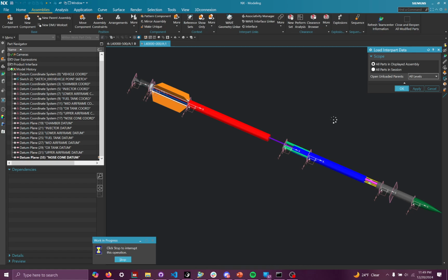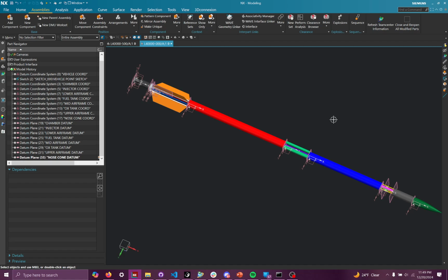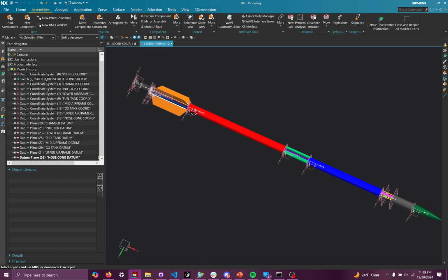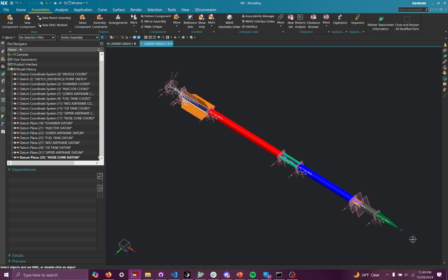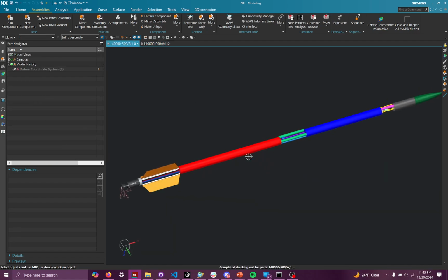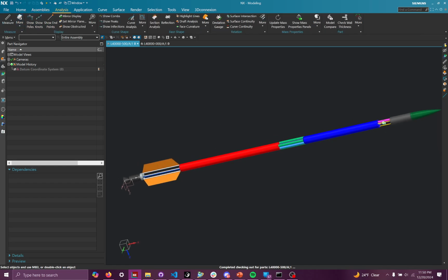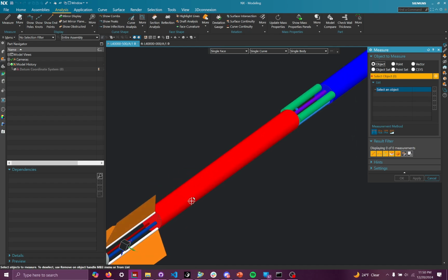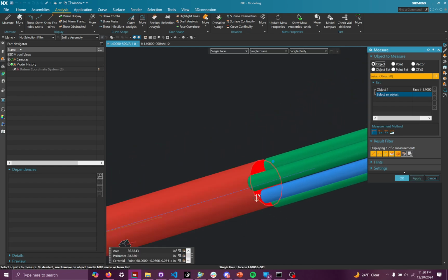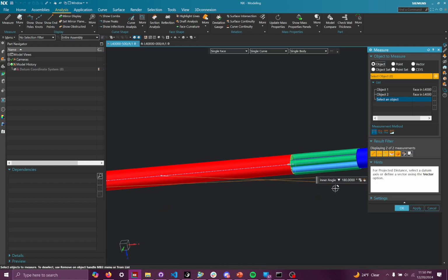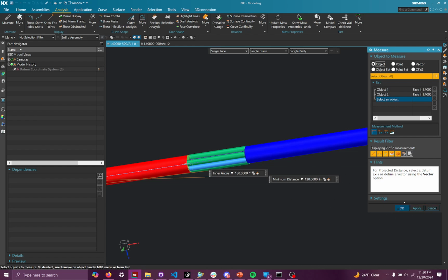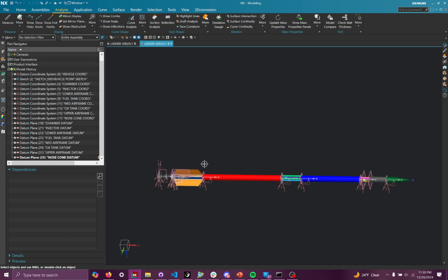And you'll see a bunch of things kind of shift around a little bit as that change gets propagated throughout all the subassemblies' layout files. And there you go. Things change length. The fuel tank updated to be 120 inches rather, and everything else shifted upwards to match it. I can actually go into this vehicle assembly file, and I can check the length of the fuel tank just to double check that it made its way into the vehicle assembly file as well. There you go, 120 inches. So the change did propagate properly.